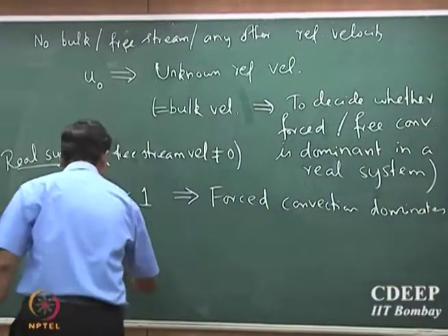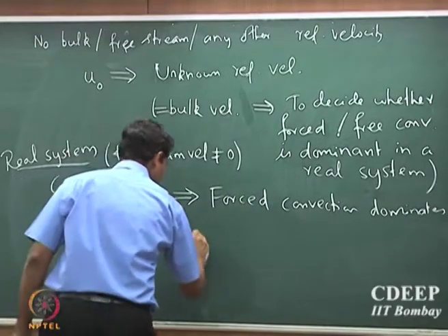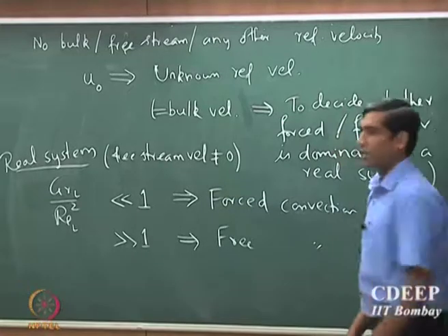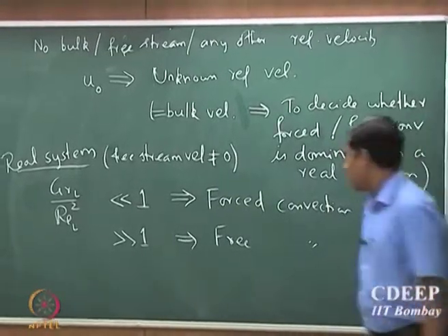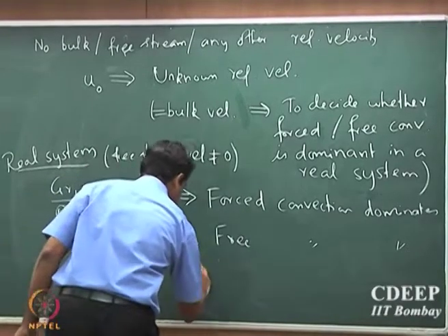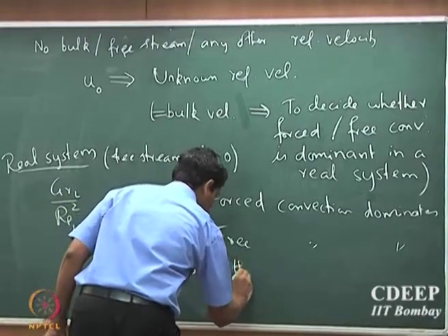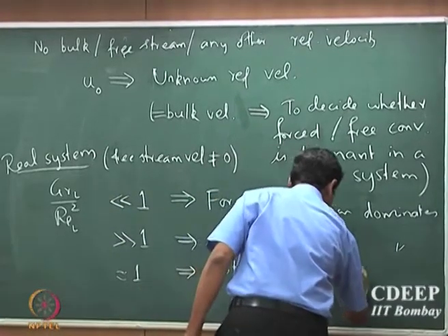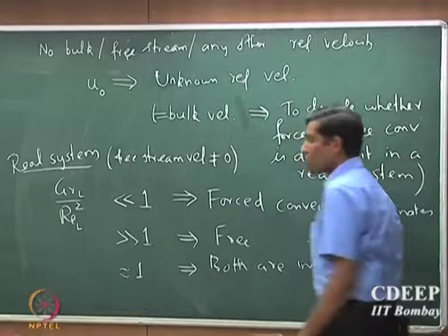If it is much larger than 1, free convection dominates. And if it is almost equal to 1, then you would expect that both are important.